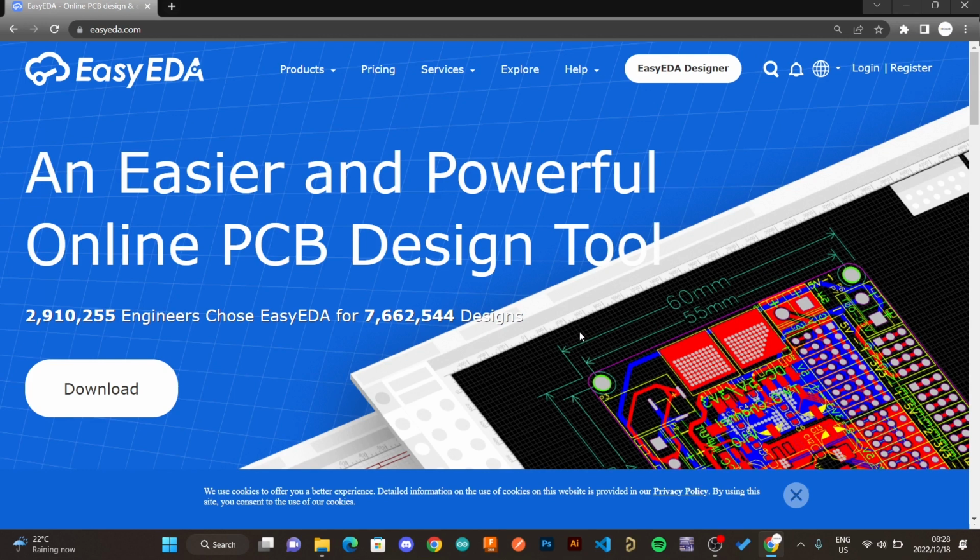So it's going to be very exciting. So let us start. In order to download easyEDA, you have to go to this website called easyEDA.com. Once you are on that website, there are two options. You can actually use easyEDA online without downloading the desktop client. You can see here we have easyEDA designer. Once you click here, you'll be prompted with the same interface as the desktop client, but once you go to download, you have the desktop client. So let us click download.